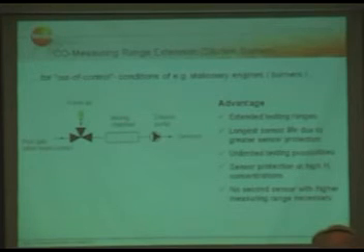That means, just a simple example, if you have 100 ppm H2 in the flue gas and the cross sensitivity is 60%, it's 60% of 100 ppm, so the CO reading will be 60 ppm wrong in addition to your current CO reading.